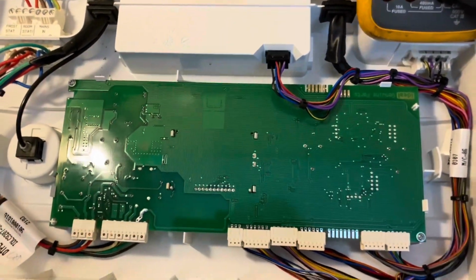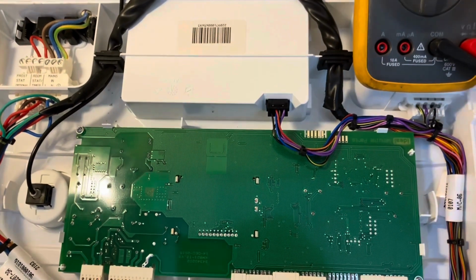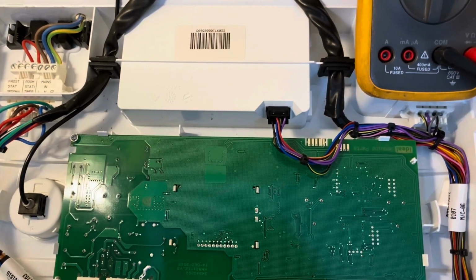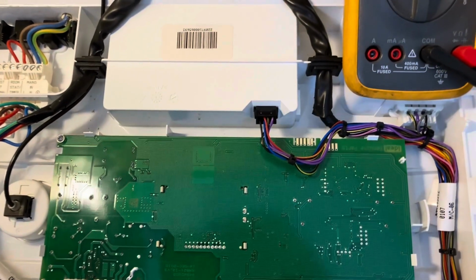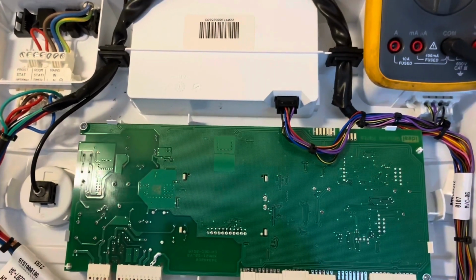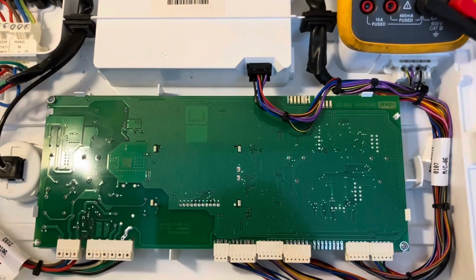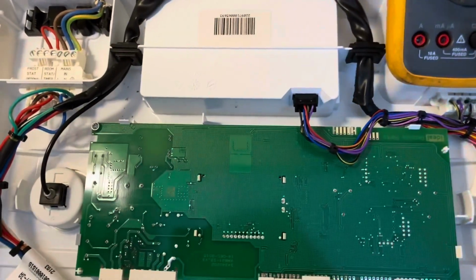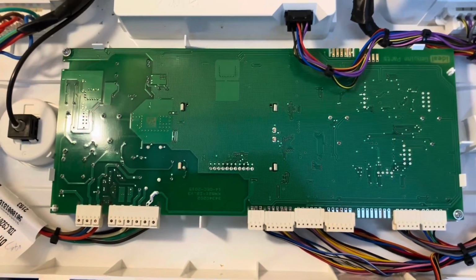Right, so we've determined that the incoming power cables are in good order, the correct way around with the polarity. There's no short circuits, no damage to the cables, and we know that any faults on this boiler would have nothing to do with the incoming supply. So we've ruled that out, and we've ruled that it's safe to work on. So now we're going to do some dead tests on the boiler. So the power's off.